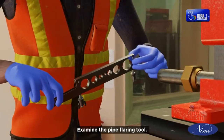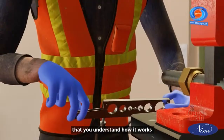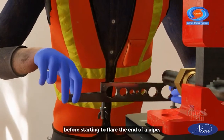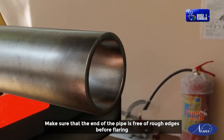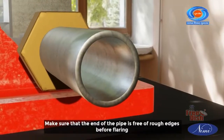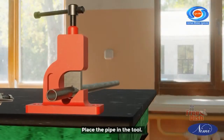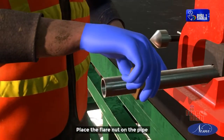Examine the pipe flaring tool. Make sure that you understand how it works before starting to flare the end of a pipe. Make sure that the end of the pipe is free of rough edges before flaring. Place the pipe in the tool. Make sure that you have placed the flare nut on the pipe.